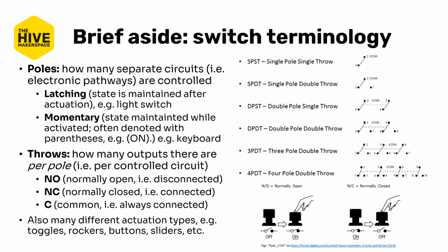With shorthand being SPST for single pole, single throw, or 4PDT for quad pole, four pole, double throw. Single throw switches will often also have a notation for whether they're normally open or normally closed, meaning NO or NC.